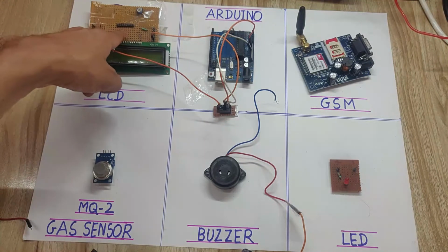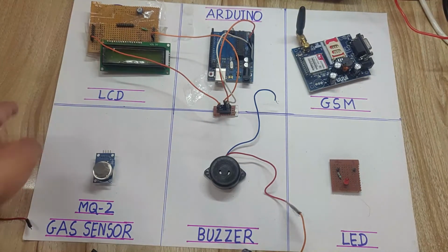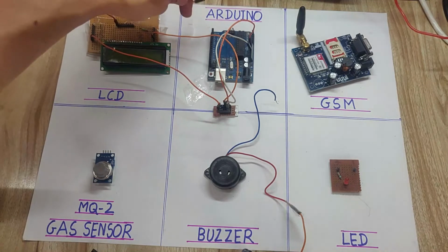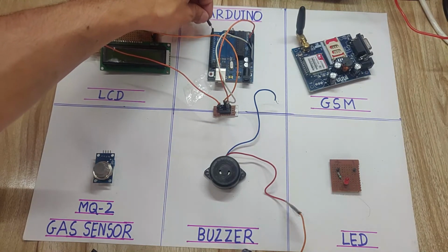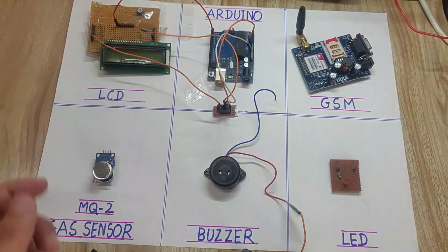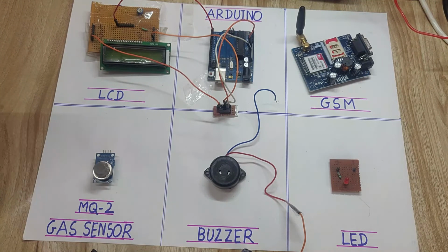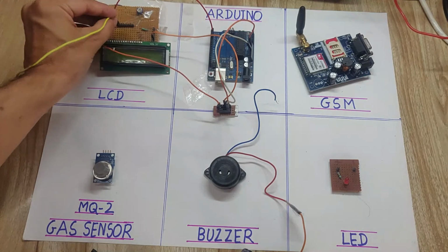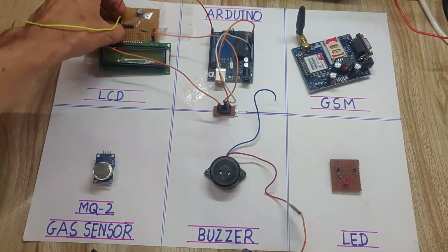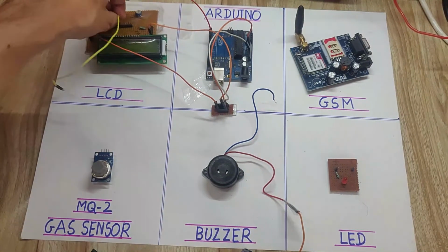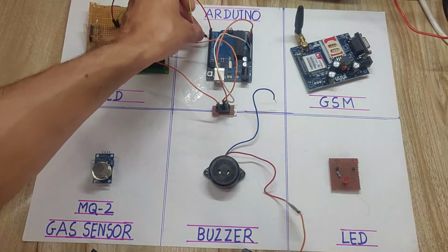Now the next part is we have to connect the input pins of this LCD that I already explained in the video. So first pin is the RS pin. The RS pin of this LCD should be connected to pin 4 of Arduino. So take pin 4: 0, 1, 2, 3, 4. So connect the RS pin to pin number 4 of Arduino. Now the next pin, the enable pin of this LCD, that is the second pin from this berg strip. So this is the enable pin, and this should be connected to pin 5 of Arduino. So connect the enable pin to pin 5 of Arduino.